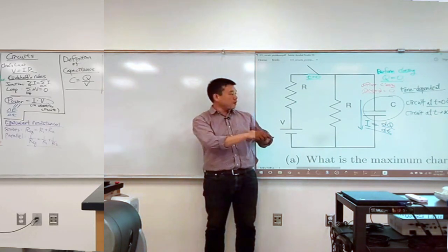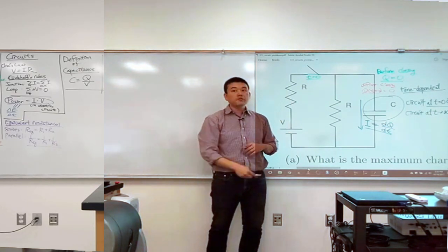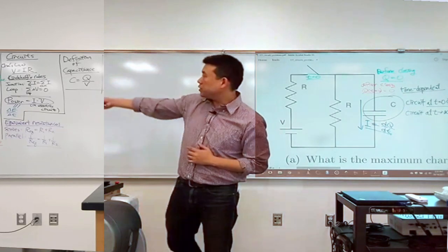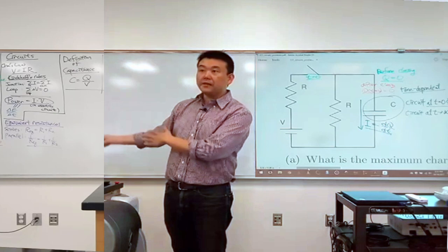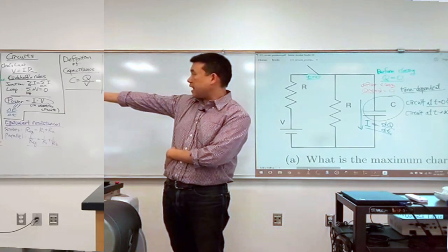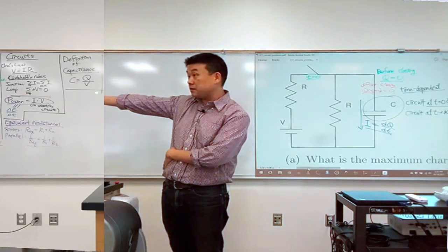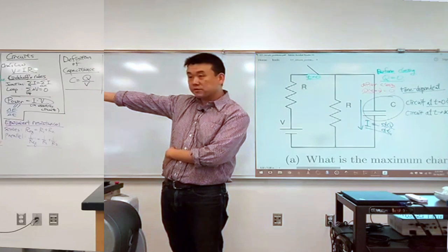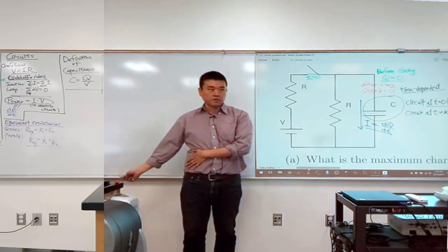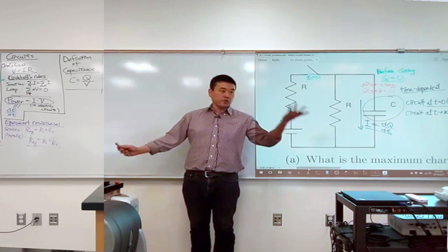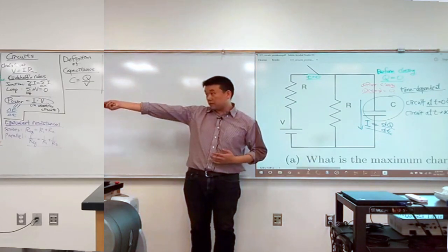If we want to know the voltage of the capacitor, the very first thing you go through is the definition of capacitance. That's why I'm telling you now that this is as important in dealing with the capacitor as Ohm's law is in dealing with the resistor. Whenever you want the voltage difference across a resistor and you have the current, you would go through Ohm's law.